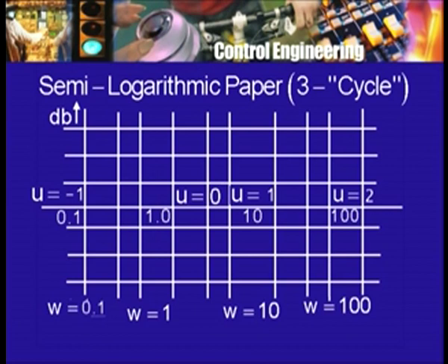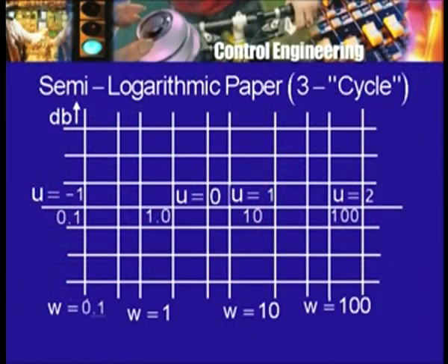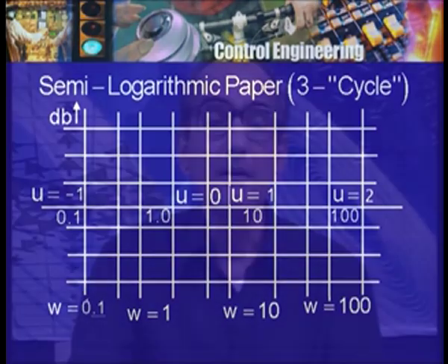So you have to take the semi-log paper and then make markings on it like this, corresponding to omega equal to 0.1, 1, 10 and 100. One does not usually even write omega. It is understood that it is omega which is being shown logarithmically along the horizontal axis. And then we have to choose the vertical location of our graph, because all we have on the graph paper are simply equally spaced lines, lines which are equally spaced vertically. They may be 1 centimeter, the major lines may be 1 centimeter apart, or depending on what kind of paper you have at a closer or greater distance. So that does not matter.